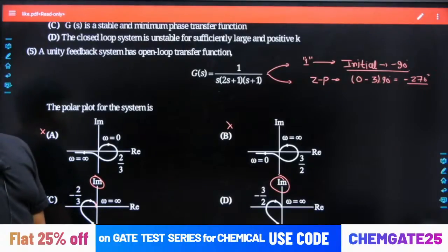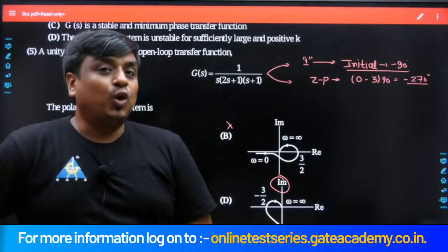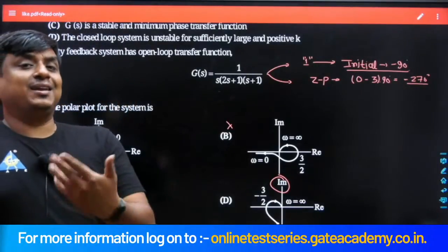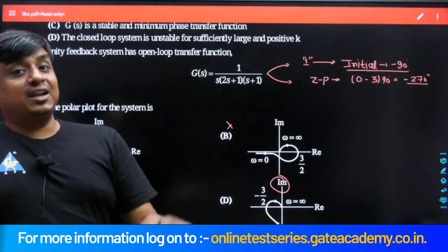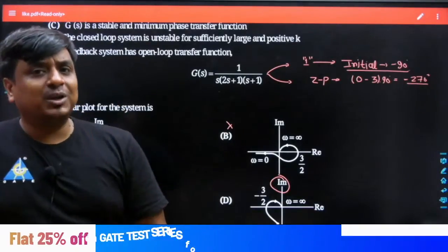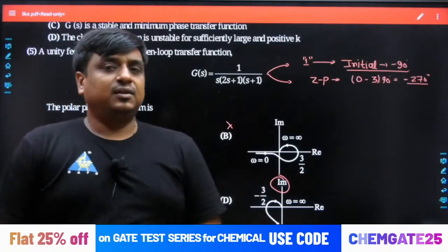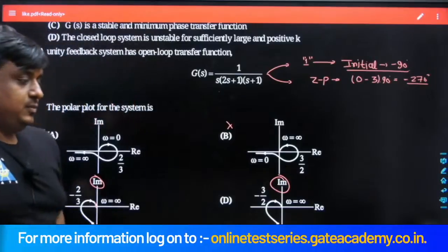Again, you find the value of omega pc, that is nothing but the frequency at which the angle offered by the system is minus 180 degrees, or I can say the intersection over the negative real axis of the polar plot. Taking the reference of that omega, we would again find the magnitude offered by the system, and at the end of the day our work is done.